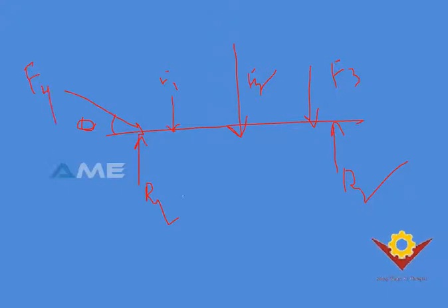See, these are planar in the xy plane. These are the forces which are acting on an xy plane or xz plane, any two planes. Those are coplanar, and moreover these are not concurrent, so that's why you're calling them non-concurrent forces. So for this type of system of forces, you can find the resultant by the method of resolutions.